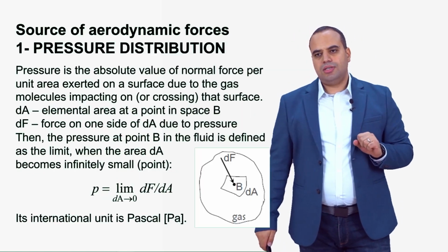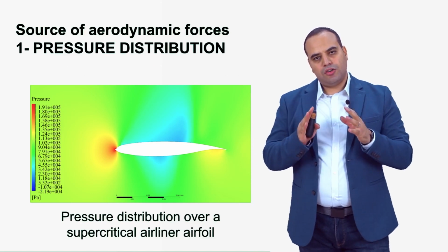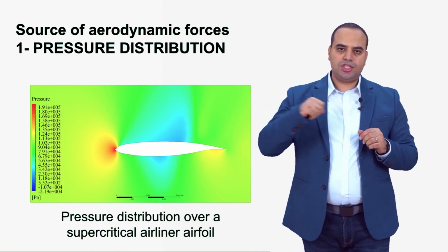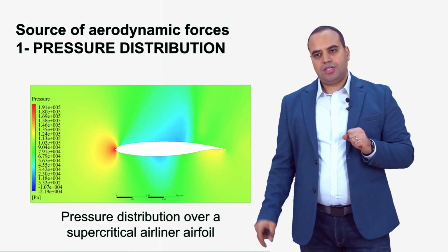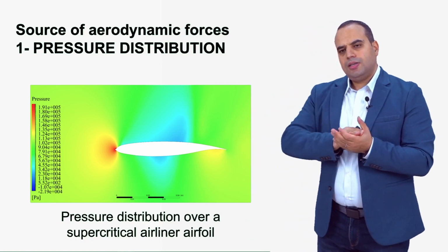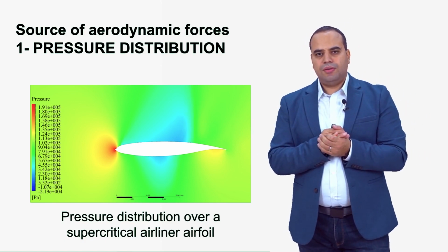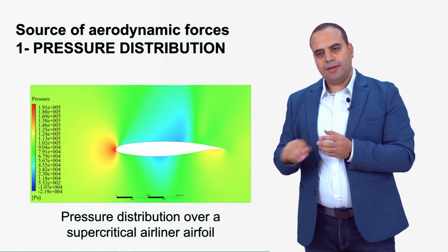But what the airfoil feels, it feels this picture, right? So it feels a lot of pressure on its leading edge, right? Why? Because it's the leading edge attacking the gas, right? So the leading edge is attacking the gas at a certain speed, which may be very large. So in fact, this picture here is at very large Mach numbers, very large speed, in order to have that large amount of pressure, which is written here in pascals. You can see the legend there.